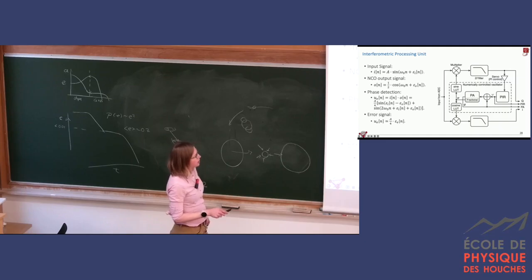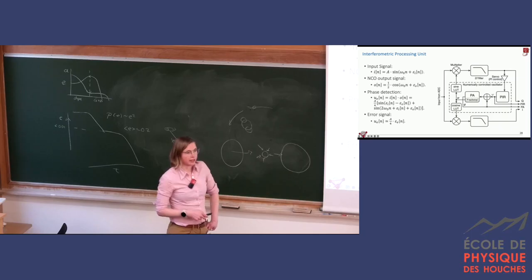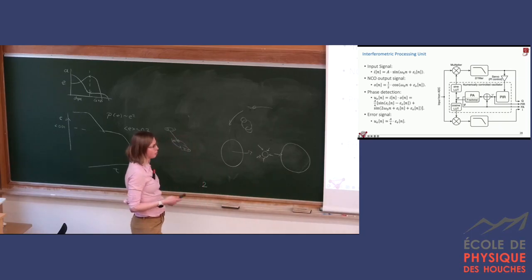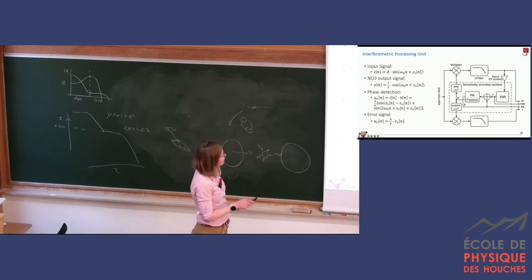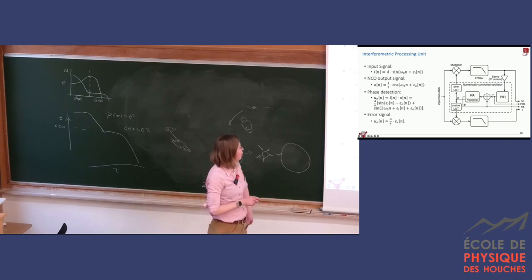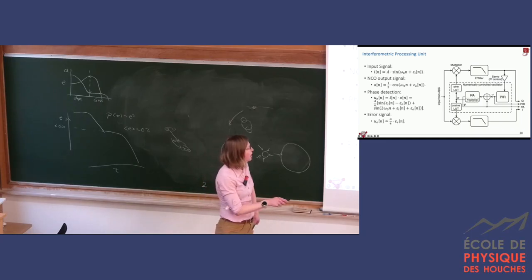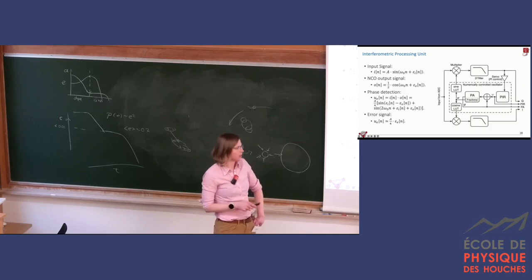Now, what is of interest is called the Q, or quadrature component, and it's directly proportional to our phase. If we mix those two signals, we get something that has a sine component, proportional to the difference between the phase of the incoming signal and the instantaneous phase of our copy of the signal.